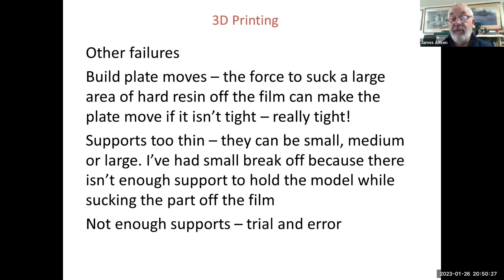The supports can be too thin. I showed you that you've got light supports, medium supports, and heavy. I have had plenty where the supports have come out beautifully and I've got no model attached to them at all, because they've simply broken off. So you've got to get it right, and it's extremely frustrating. And not enough supports. Trial and error and experience. You'll build that experience up over time.